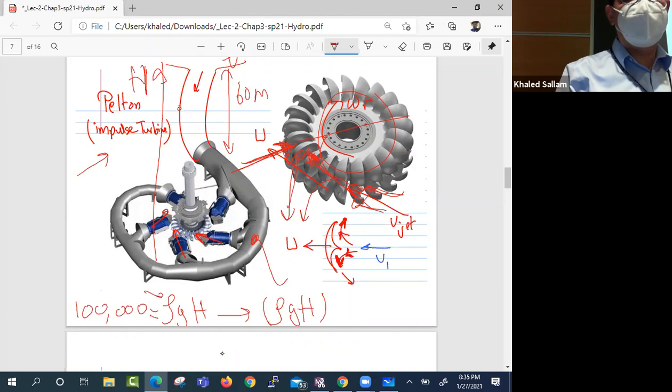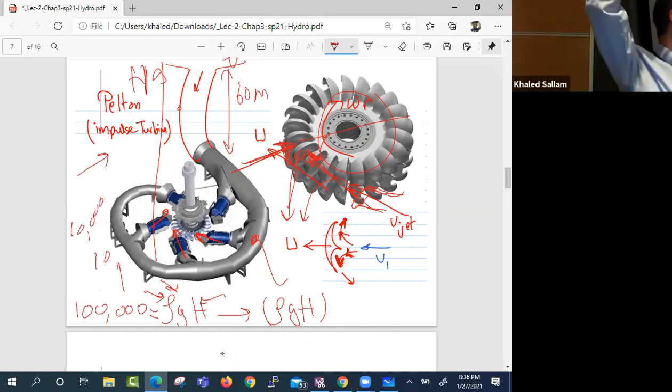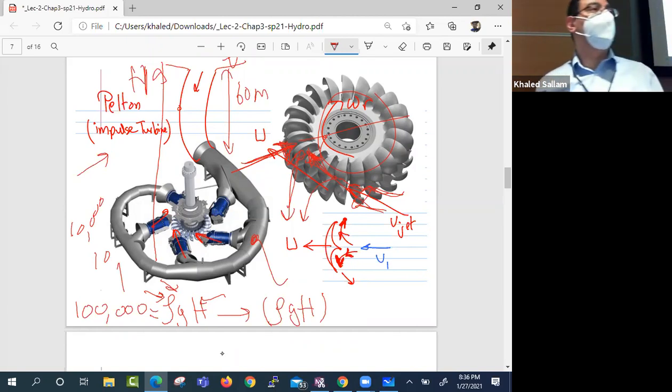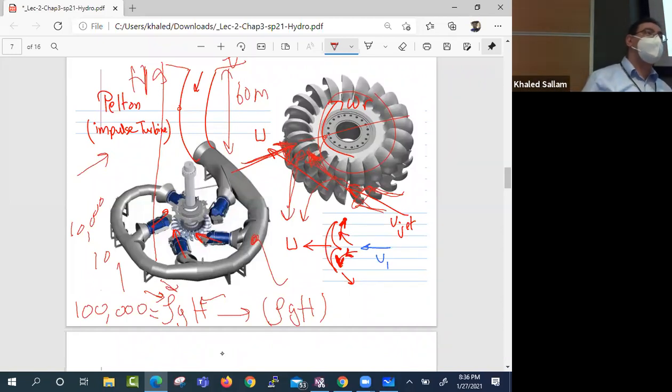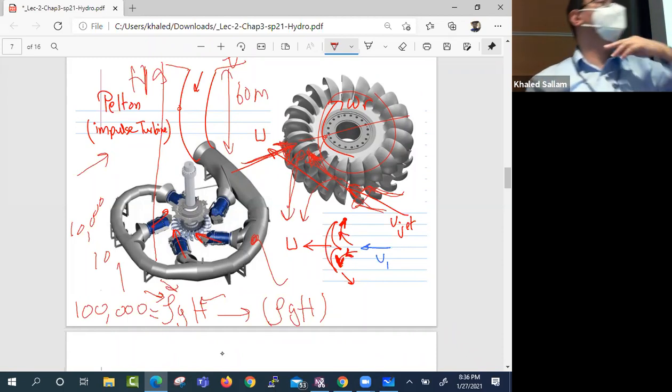What is rho g H? Rho air, which is 1.2, let's call it 1. g, which is 9.8, let's call it 10. And H, which has to be 10,000. So the 10,000 meters of air on top of my head, multiplied by g, which is 10, multiplied by rho, which is 1. That's how I get my 100,000 Pascal on top of my head. Right? And if you go to the swimming pool, you only need what to get 2 bar?